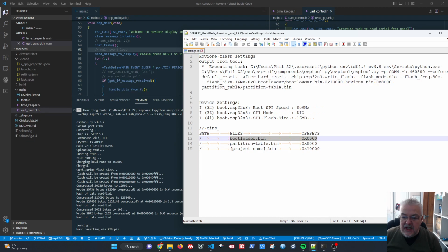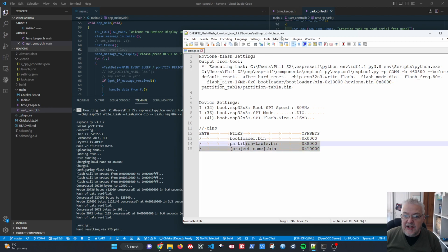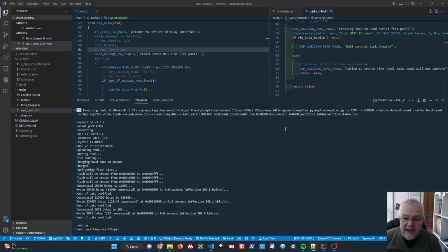So this will change. There's huge flexibility in the Espressif chips. You can change the size of the partition tables, you can do all sorts of fancy stuff and move things around to optimize your code space, or if you want to have different partitions for, say, a file system or whatever. So we need to load them in. If we have made a custom partition table, we need to point at where it is and all these sorts of parameters with it. The S3 seems to use this as the default, but we don't have to guess, because that's the reason we flashed the chip, so we can get this information.